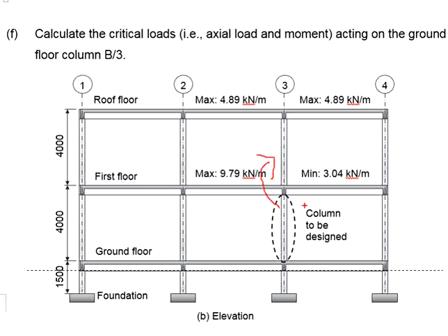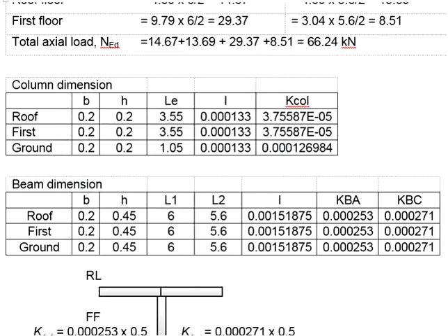the fixed end moment from both beams, get the balance, get the stiffness, and get the distribution factors in order for us to acquire the amount of moment taken by this column. With this understood, we will need to first get the stiffness of the columns as well as the beams. In order to get the stiffness, we need to first know the properties of the members.